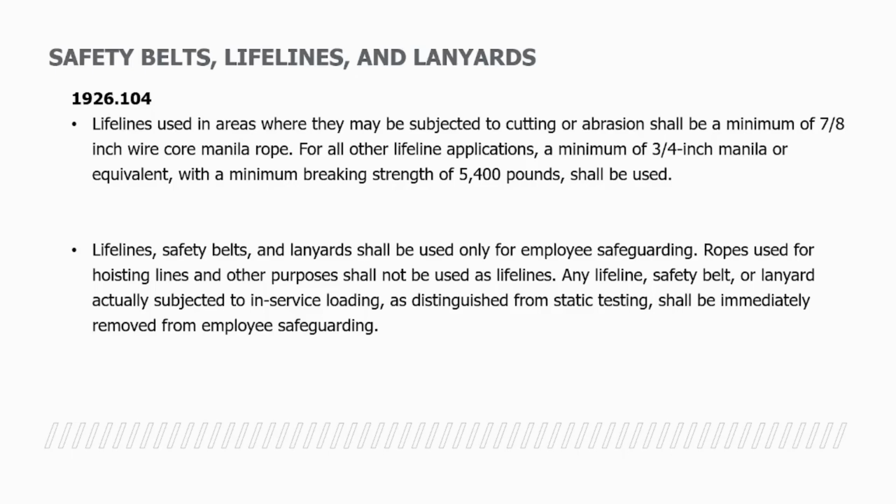Any lifeline, safety belt, or lanyard actually subjected to in-service loading, as distinguished from static testing, shall be immediately removed from employee safeguarding.